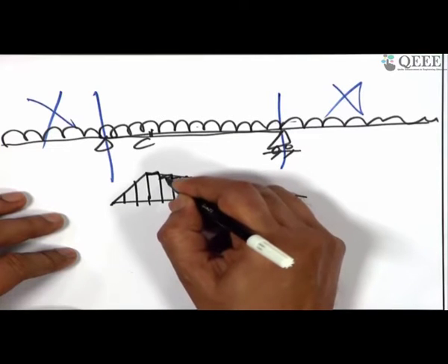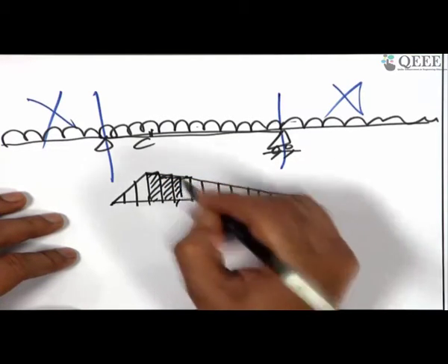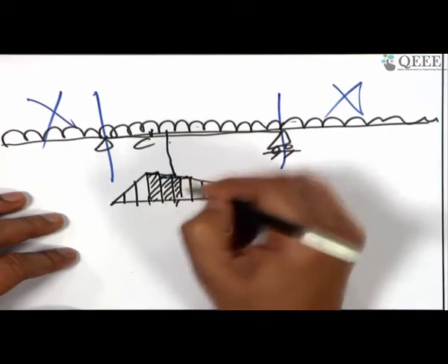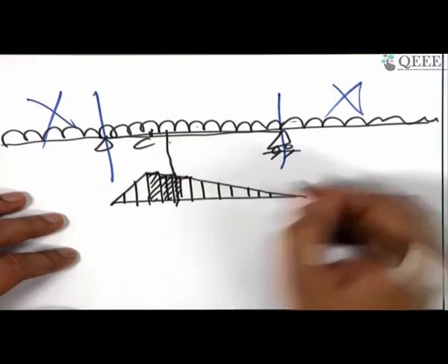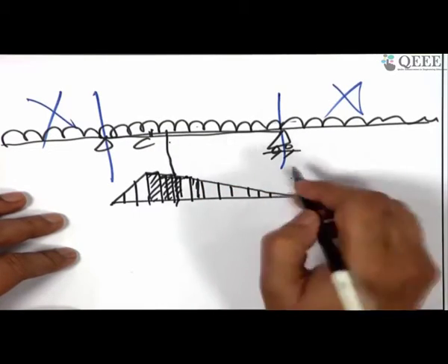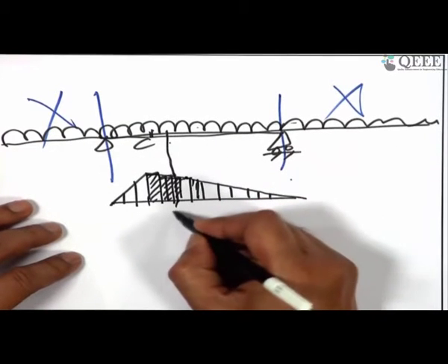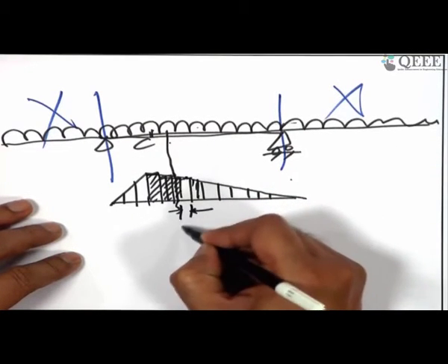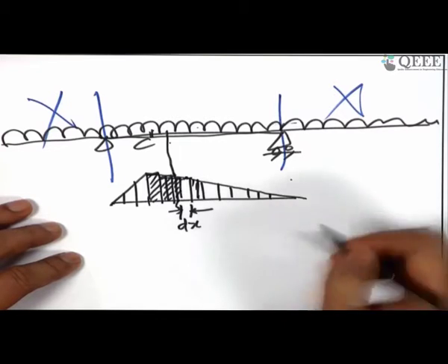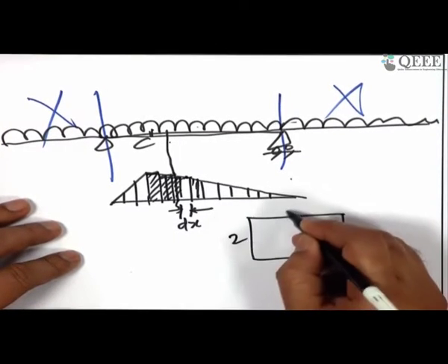You will be left with several rectangles, the area of which will describe the ordinates, and the midpoint of that is the ordinate. So you will have small rectangles and their ordinates, and you can apply the first formula, which is for the concentrated load, and you will get the same answer in the limit if you reduce this dx length. That's it.